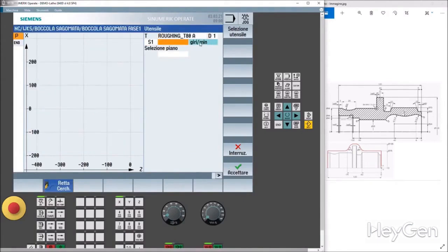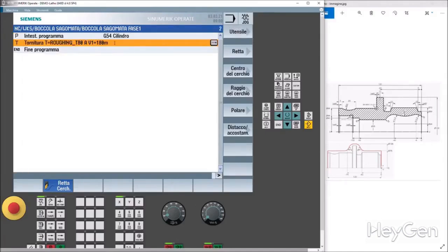And tell it, look, I'm going to have you work not in revolutions per minute, but as a lathe operator, so in constant cutting speed, 80 meters per minute in the turning plane. And I accept. This is our equivalent, which is commonly known and referred to as T0101 M6. Depending on the machine you're working on, M6 often rotates the turret.